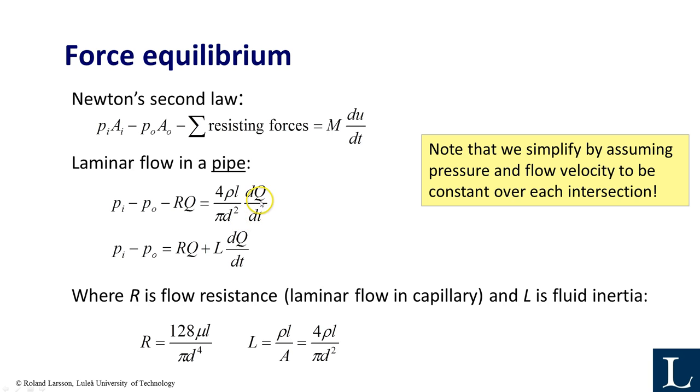Well, maybe a bad explanation here, but if you want to change these to something we already know, we know the diameter of the pipe, we know the density of the fluid, we know the length of the pipe, and then you can rearrange this to something that looks like this, and you then also can identify this as an inertia coefficient or inertia constant.